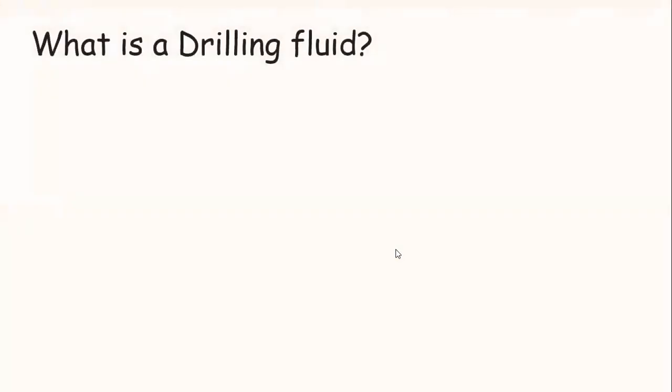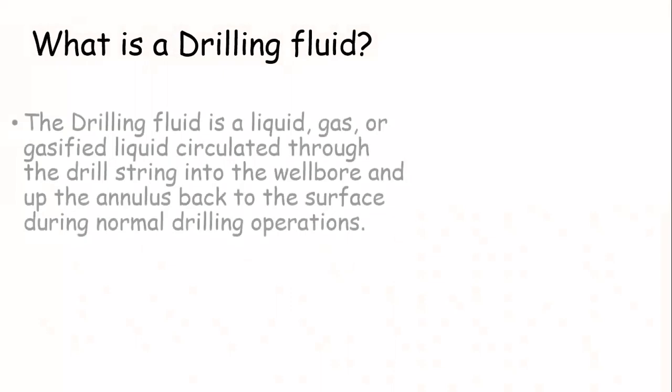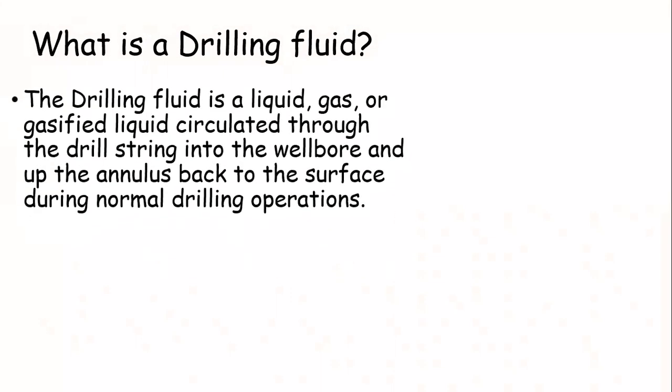So firstly, what is drilling fluid? Drilling fluid is a liquid, or it could be gas, or a gasified liquid, which is circulated through the drill string into the wellbore and up the annulus and back to the surface during drilling operations.